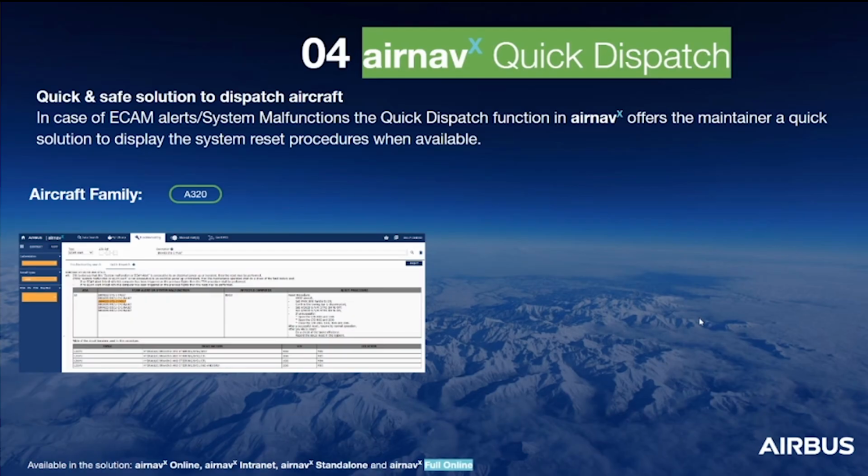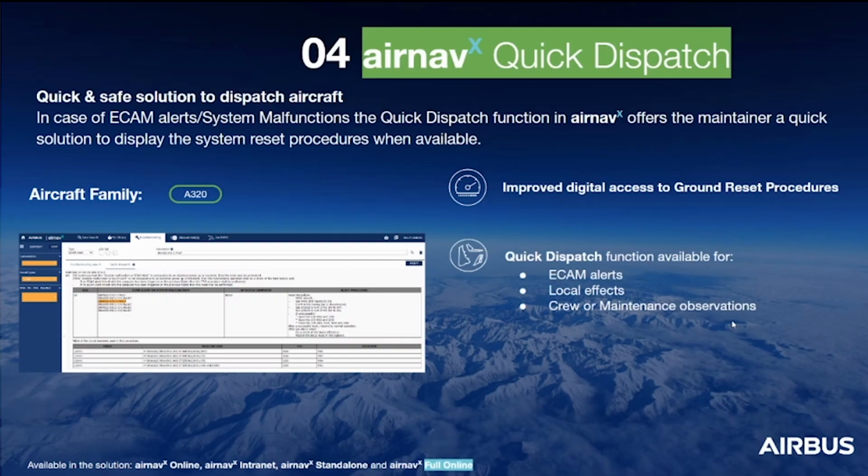This function offers a quick solution to access the content of the TSM on A320 family system reset guidelines and quickly display the related ground reset procedures when available. The aim is to clear the failure and safely dispatch the aircraft. This function is available for ECOM alerts, local effects, and crew ops for which the reset is allowed with restriction.